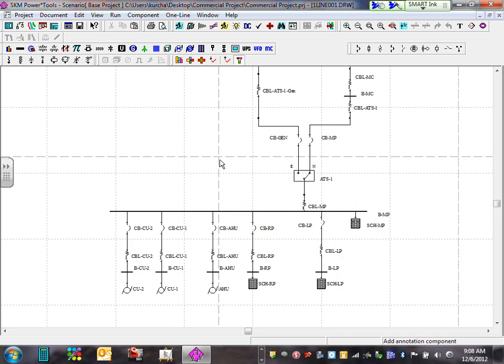Okay, now I'm going to coordinate the air handling unit, not the chiller, with the circuit breaker for the air handling unit and with the main. So this will allow you, Darren, my friend, to say this circuit breaker will protect the air handling unit, number one. Number two, allow the air handling unit to start. Number three, if you have a short circuit in the air handling unit, you want that circuit breaker to trip, not the main.